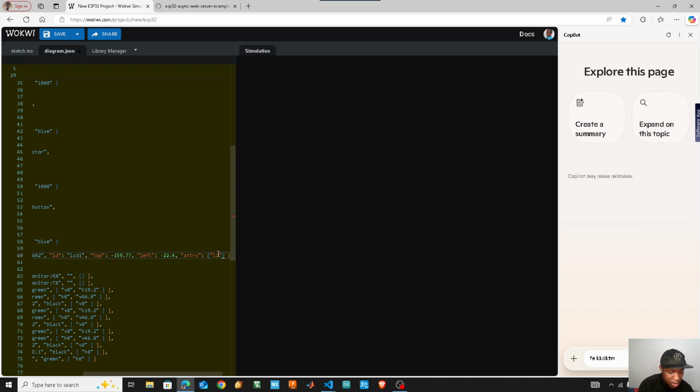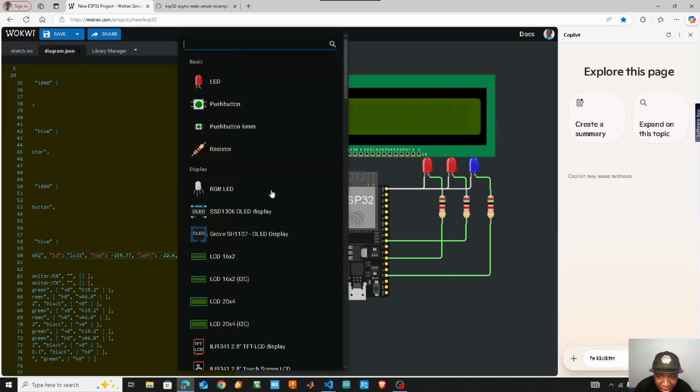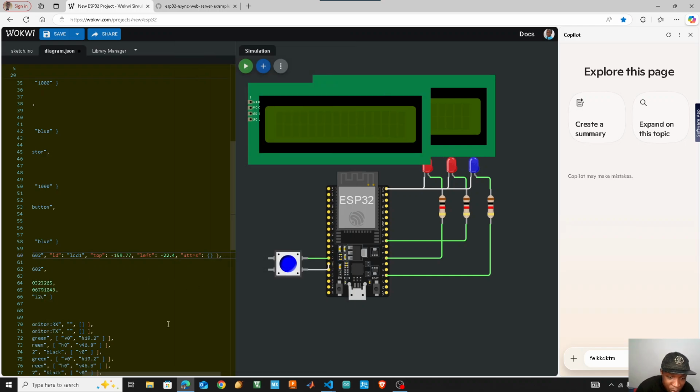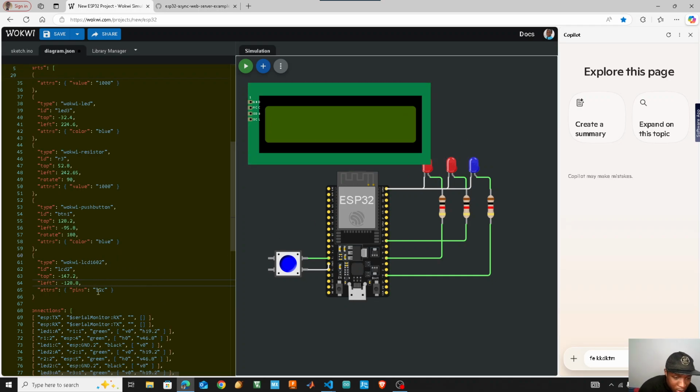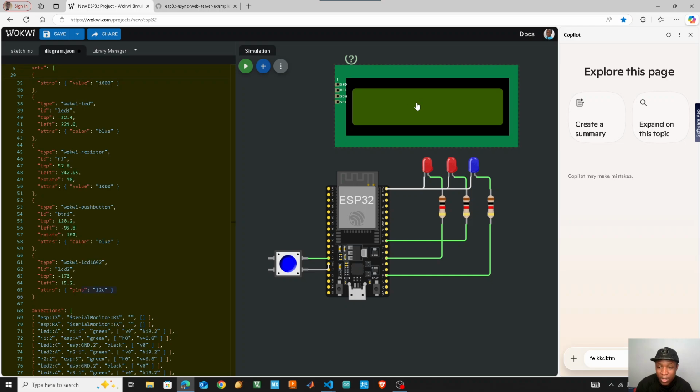Or I2C. Yeah, I want to make it I2C ones. So the attribute is what for I2C? Let me first get rid of this one. Yeah, it's I2C pins. You have to add the attribute name, which is pins. Okay, so I'll add this one.